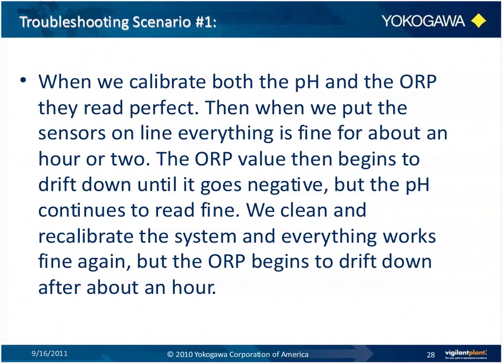The first is that the platinum is saturated or fouled. This one is difficult to correct. You can try to reactivate the platinum by inserting it in a strongly oxidizing or strongly reducing solution for about 8 to 24 hours. If that doesn't solve the problem, the second possible problem could be what's known as electrical polarization. For this, you need to actually check how the sensors are connected.